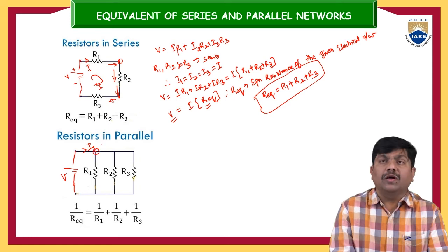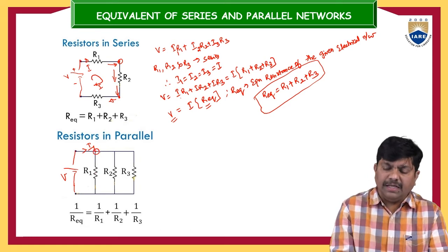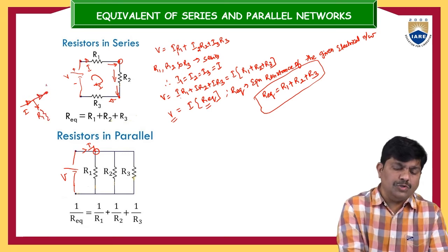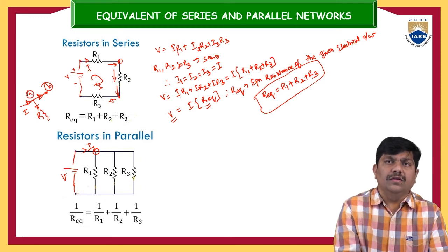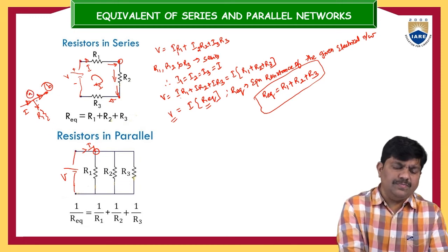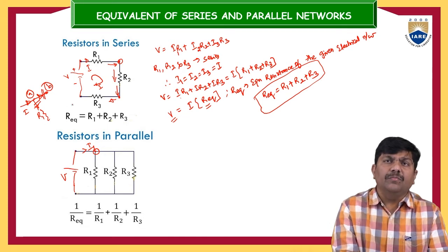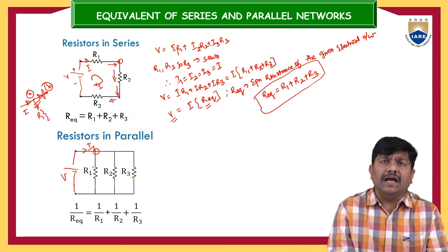At this particular node, if you observe, the current is finding two paths. One current I is coming like this, and it is divided into the R1 resistor and another path. This is approaching node B, and this one is assumed as A. So the current is dividing at this node A, and this branch and this branch are in parallel to each other. Just now we discussed that as long as the current remains the same, the elements are assumed to be in series configuration.